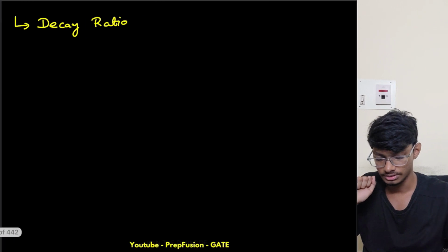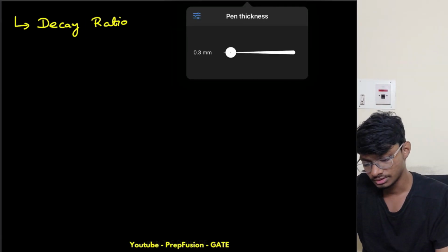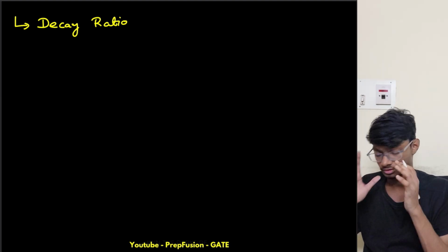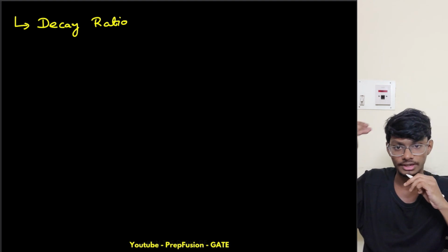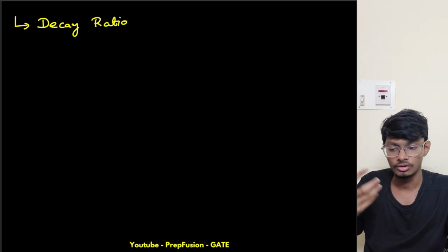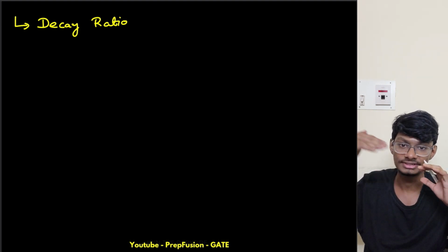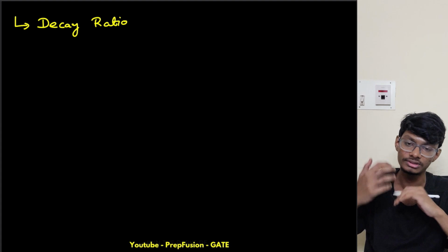Okay, so now let's understand the decay ratio. Decay ratio is basically the second overshoot divided by the first overshoot. Why? Because I'm measuring how much it is decaying after each period. That is why this is known as the decay ratio.